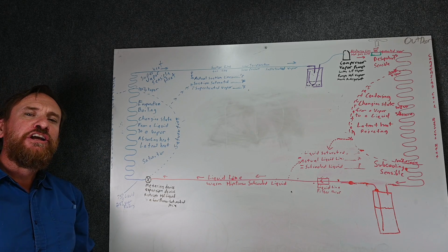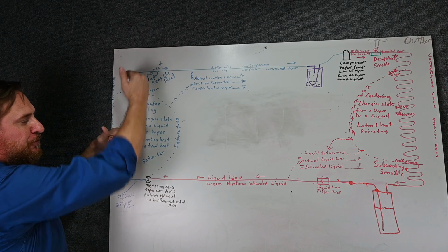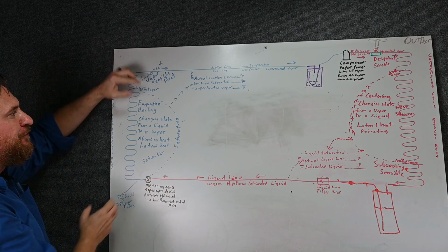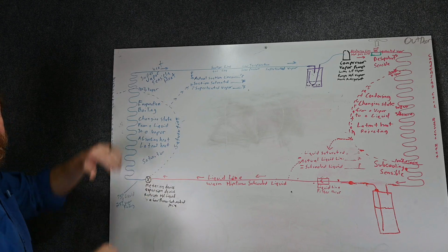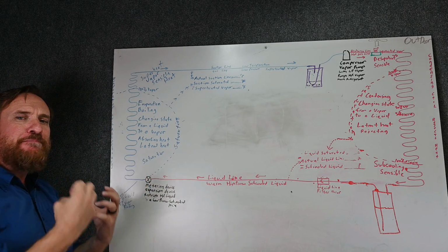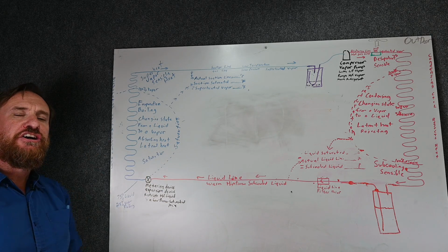That's why our target superheat for a fixed orifice metering device can sometimes have a very high number of superheat, meaning very little saturation, or it could end up with a very low amount of superheat, meaning we have a whole lot of saturation, because all these conditions affect it. But it's the saturation, it's the magic of that refrigerant boiling from a liquid to vapor. Our pressures are going to be changing all the time.